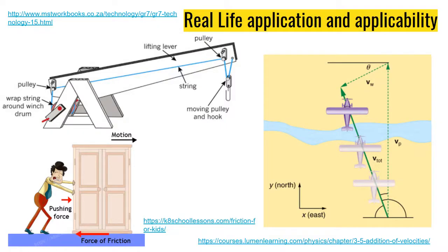The application of the concepts explored in this experiment can be seen in real life. For example, by understanding the 1 to 2 ratio of the tension forces, we can modify pulley systems to produce infinite number of ratios that will decrease the tension force required to lift a particular mass. In real life, this can be used in cranes where a pulley system allows the workers to lift incredibly heavy construction parts. Furthermore, understanding the friction coefficient is important, as friction must be overcome usually when the aim is to have motion.